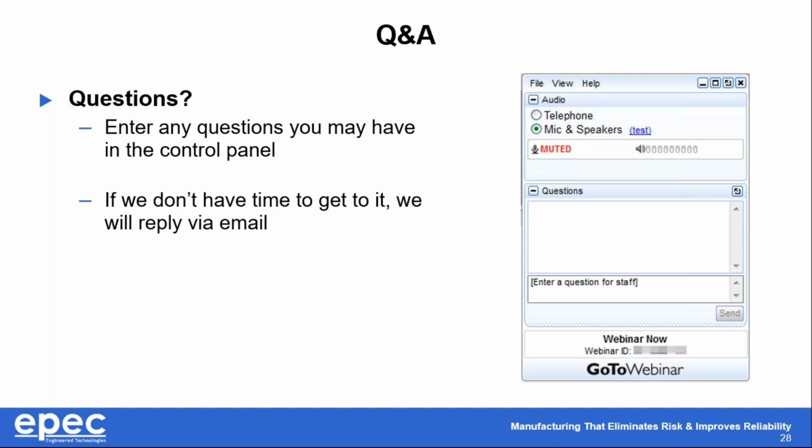If you're looking for specific UL specs that are inexpensive and readily available that we can recommend, I'd say UL 2464 is an excellent choice. That's a multi-conductor cable. It's wildly inexpensive and it's used everywhere. For single conductor wire, the UL 1007 actually has a dual certification for UL 1569, just really expanding its temperature limits.